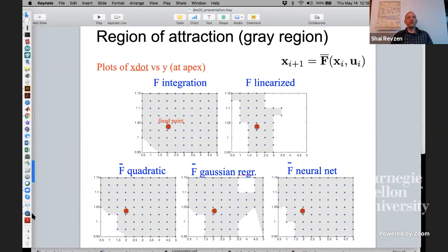There's this notion of stochastic linearization that, at least to an extent, can also be extended to higher order polynomial approximation, where instead of trying to approximate the response for specific inputs and outputs, you take a probability distribution of states and try to make something that's on average correct in the region, which would still give you a pretty concise low order model.